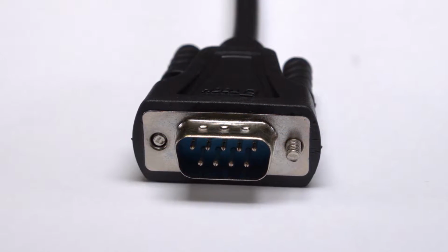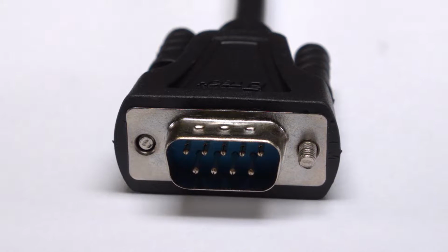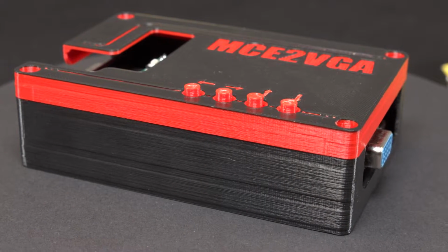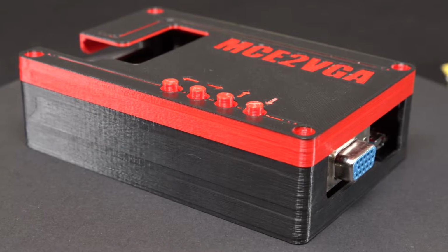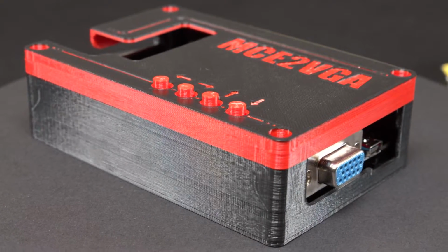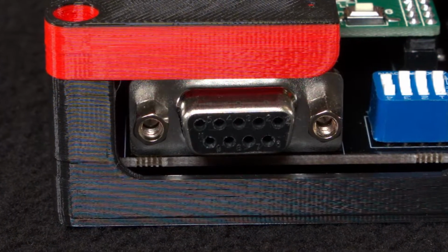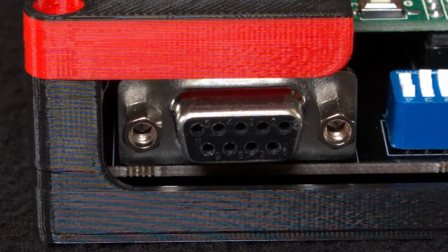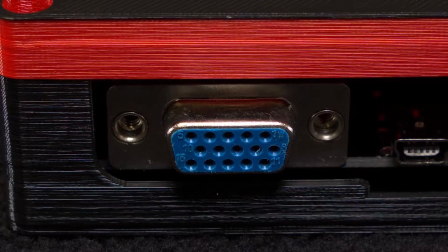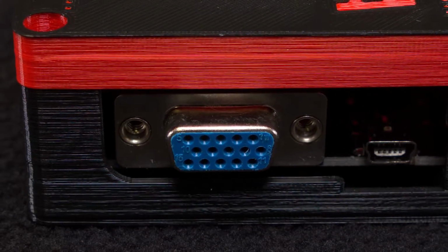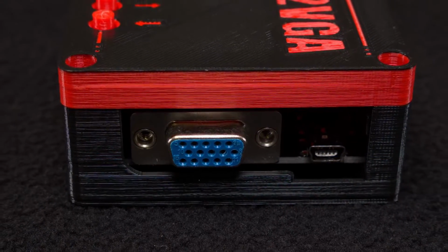In the case of a computer system using the DE9 TTL connector, things are slightly more complicated. Information about scan parameters and some other complicated technical wizardry are coded in the output signal from the computer's video controller. As we've said, standalone CGA to HDMI converters are non-existent, or nearly impossible to find unless you're good enough at electronics to modify a board designed to go into a new television and create your own enclosure, complete with other boards for whatever type of I/O you need.